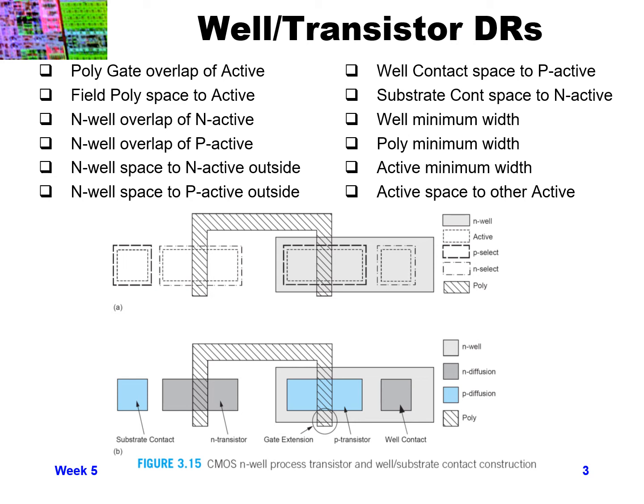A similar thing: the N well has to overlap your P active, and for similar reasons you want to make sure your P active is fully inside your N well, so any misalignment causes your P actives to still stay inside your N well.